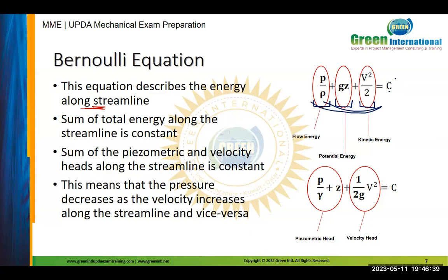20 meter head, this is pressure? Yes, because head is just multiplied by a constant, gamma, the specific weight, and you get the pressure. So pressure or head refers to the same thing. We can represent the energy equation by joule or by head, in meter or feet or inch.